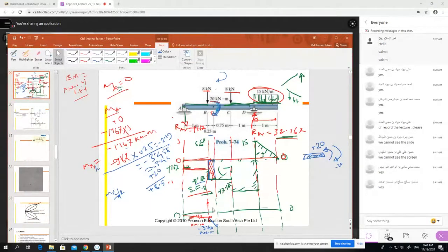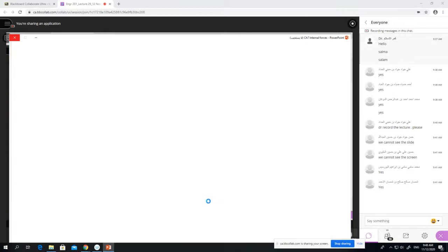Here, at the same point, the last moment at the left side is minus 3.46, and the external moment is clockwise, but the bending moment, being internal, will be anti-clockwise. So plus, that's why we write down plus here. And then after the algebraic sum, we got plus 16.5. So plus 16.5 will be here to here. Sorry, now it will take 1 minute.